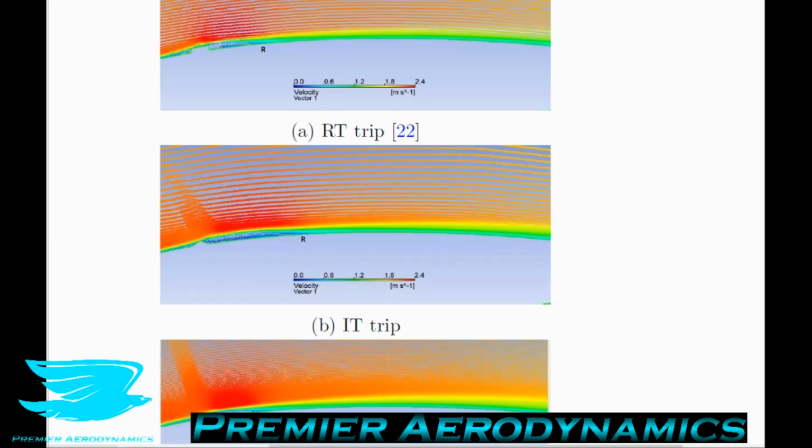For the isosceles triangle, the flow goes over the triangle, but then the back surface is not that sharp. That means there's not as much of a low pressure there, because you don't have this void that just suddenly occurs. It occurs more gradually. So the flow is not being sucked down nearly as quickly, and that means you have a recirculation zone which is much greater. So that's all what that means here.